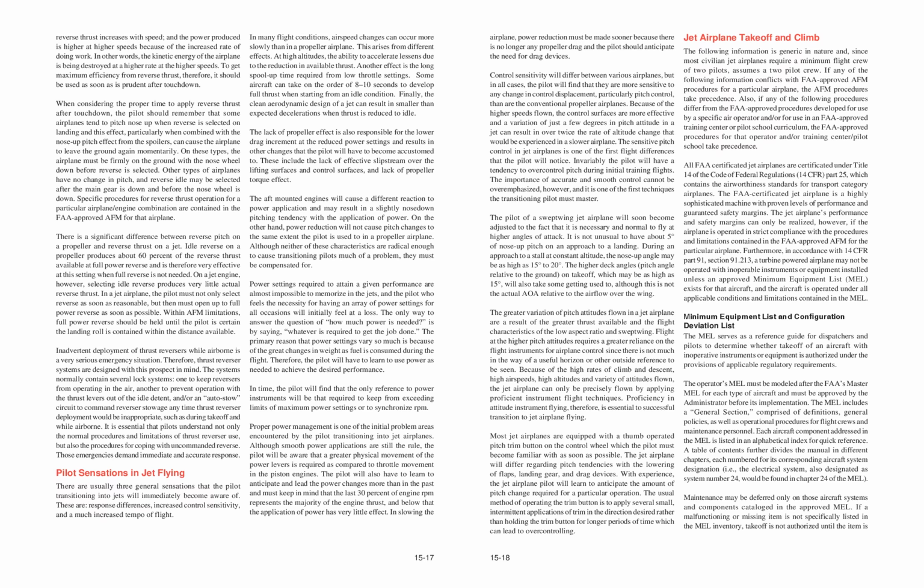Pilot sensations in jet flying. There are usually three general sensations that the pilot transitioning into jets will immediately become aware of. These are response differences, increased control sensitivity, and a much increased tempo of flight. In many flight conditions, airspeed changes can occur more slowly than in a propeller airplane. This arises from different effects.